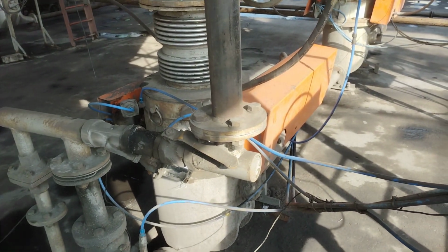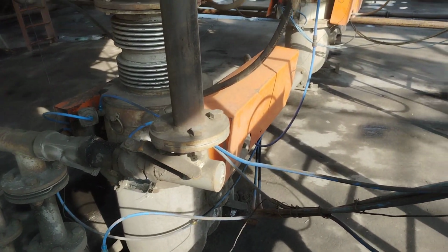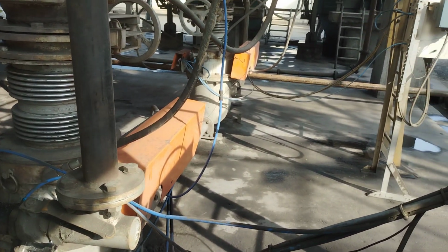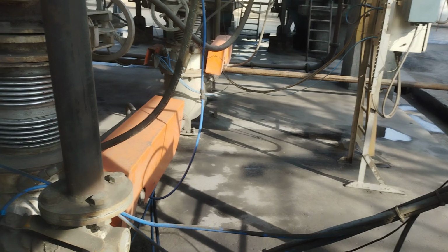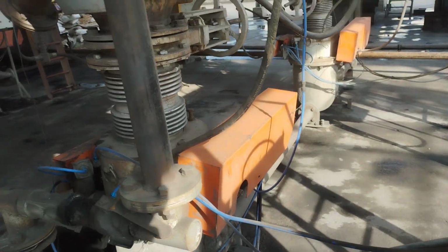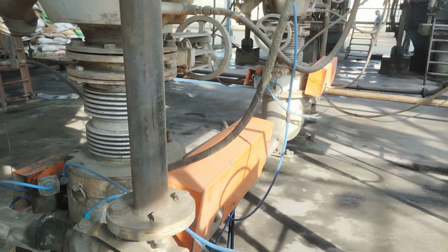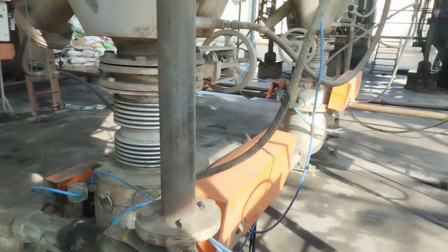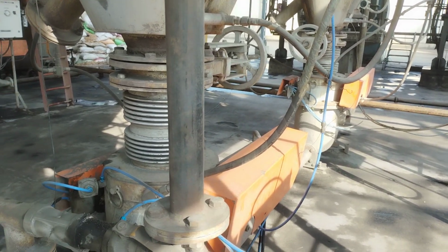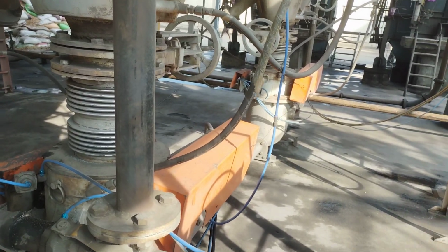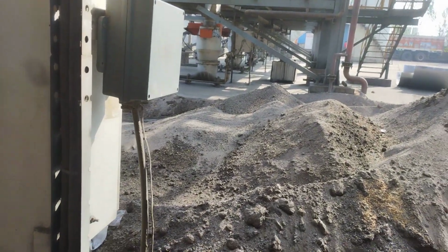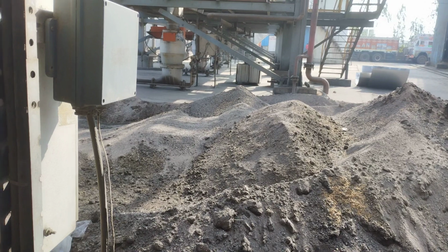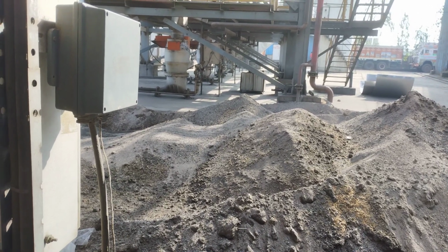Conveying completed. This conveying cycle is 45 seconds because the air preheater zone ash collection is very high. In the economizer zone, ash collection is very low. In the ESP zone, the first and second compartments are very high, and the third and fourth compartments are very low. These two are connected in series.